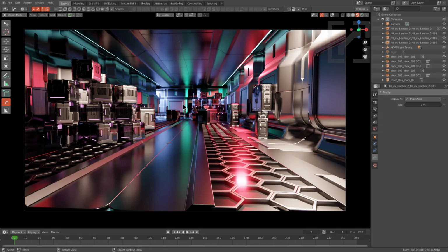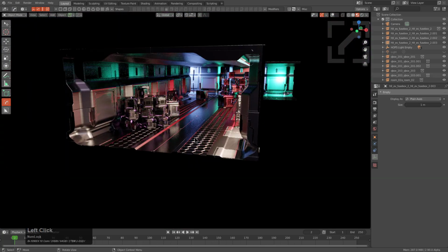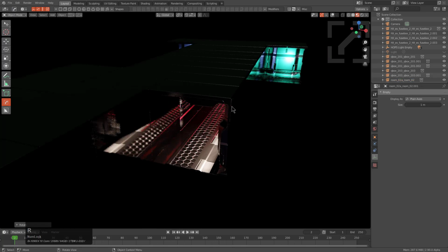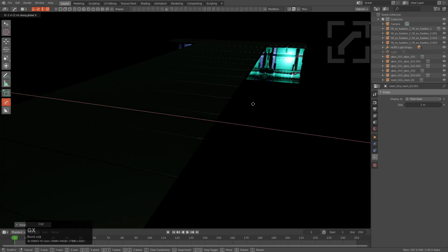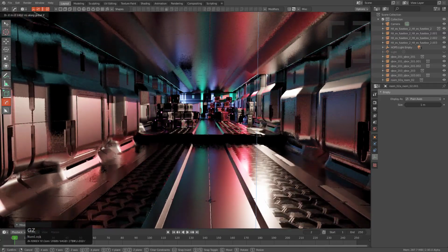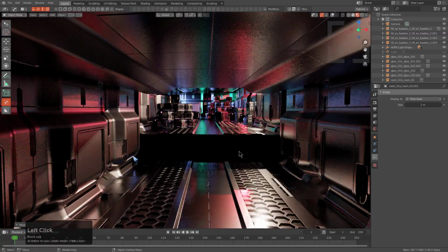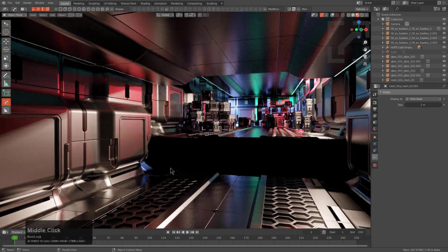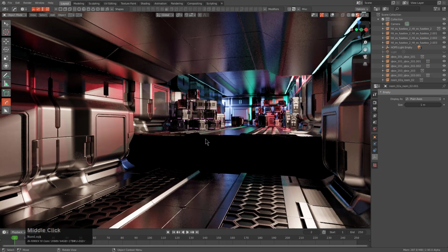To show a little bit more as far as PowerLinking fun, I'll back out of camera mode, and we'll Shift D, duplicate this main hull, and we'll just RZ twice and rotate it, and I'll just use increment snap to get it right back where we started. And so we're looking at this on the inside, and I'm just going to move it down to offset it like so. And I figured having a duplicate that was offset would look pretty cool. However, filling in this gap would also look pretty cool.